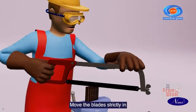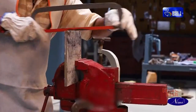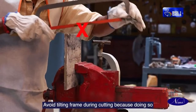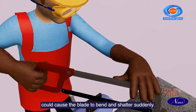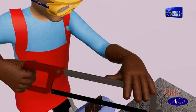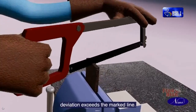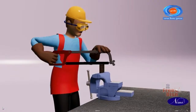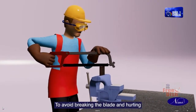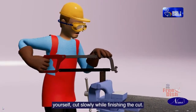Move the blade strictly in line with the marked direction. Avoid tilting the frame during cutting because doing so could cause the blade to bend and shatter suddenly. Cut from the opposite side if deviation exceeds the marked line. To avoid breaking the blade and hurting yourself, cut slowly while finishing the cut.